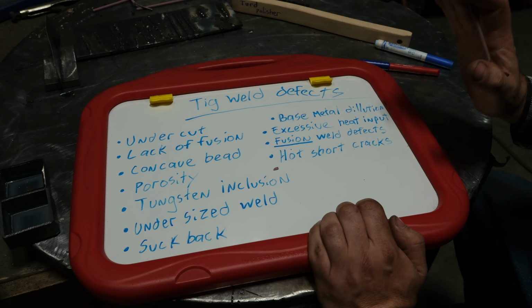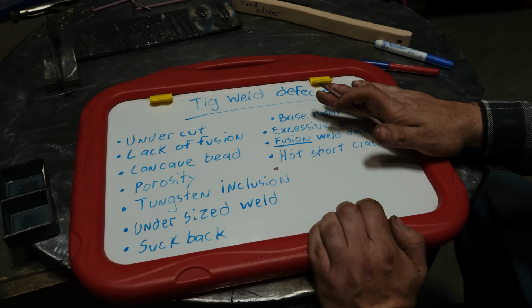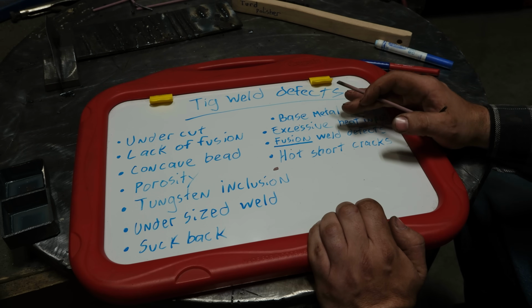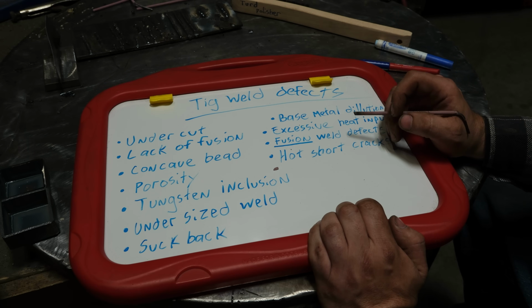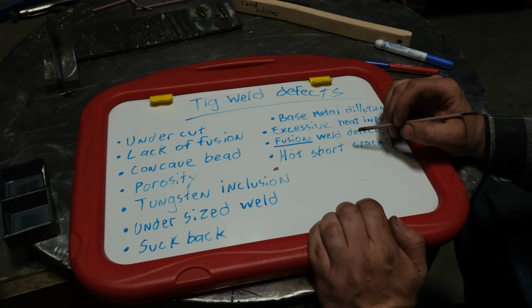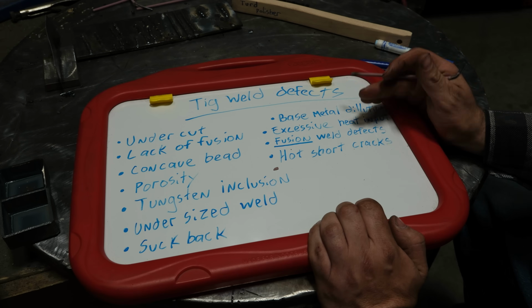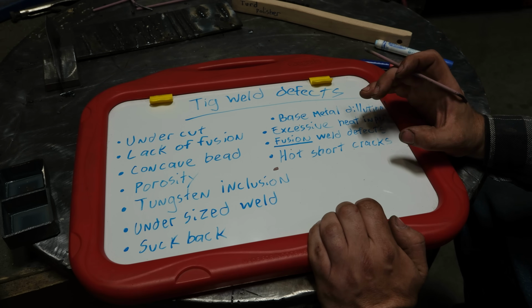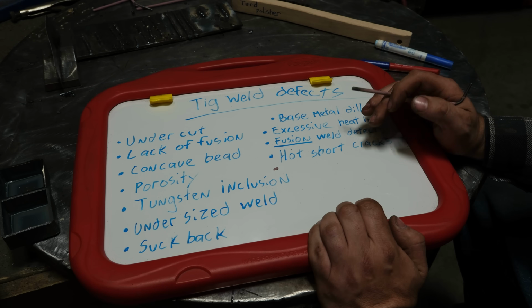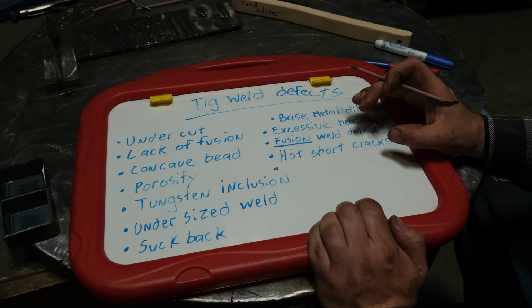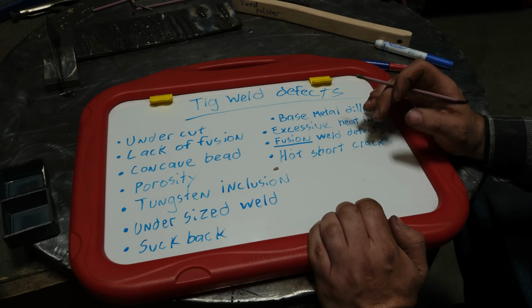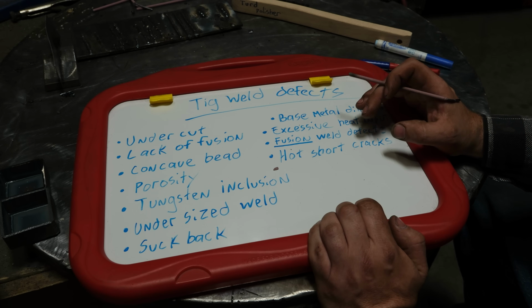So rather than slowly bringing it up to temperature, letting it stay there as you're welding, and then slowly tapering off, you do everything fast. And what will happen is the base material will often crack as the weld is solidifying. It will happen almost immediately, or it may have internal defects, which in the case of aluminum is very common, especially at craters, where if you taper out too fast with aluminum and you leave a crater, guaranteed there's going to be cracks already starting there.